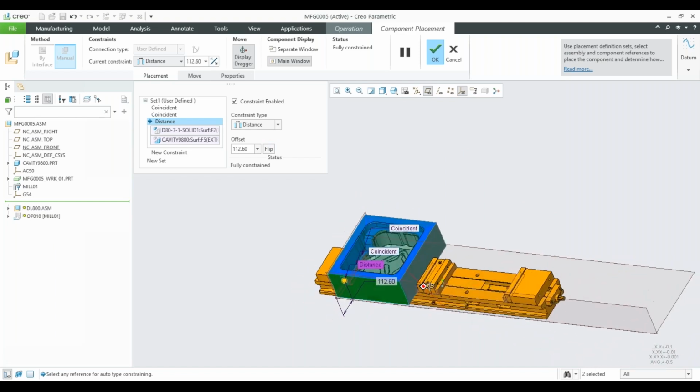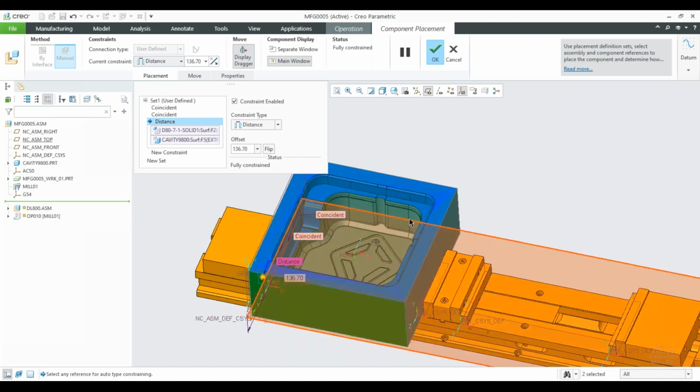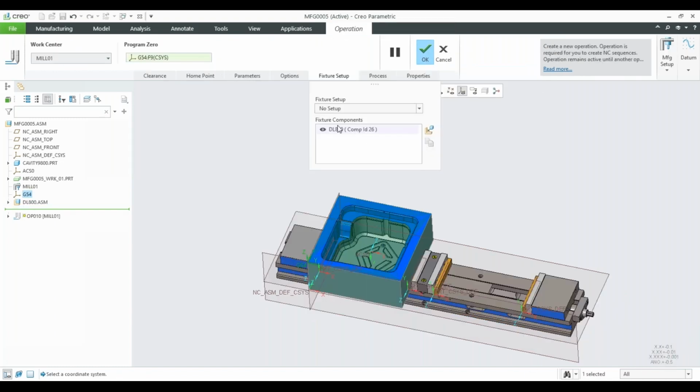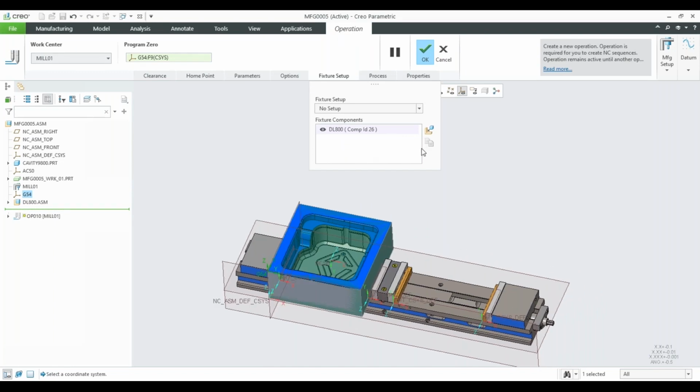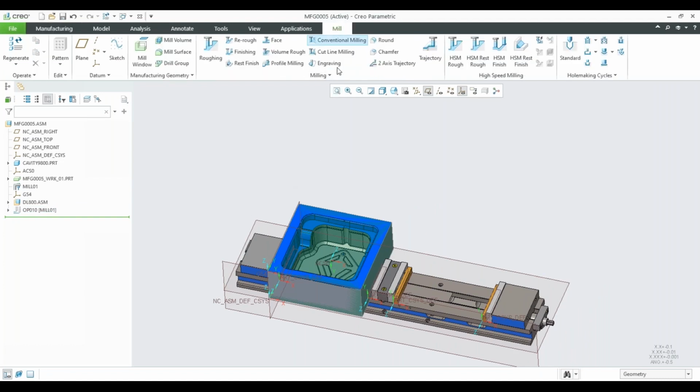If you have the exact values, use those, because if you put it wrong here, your collision detection and things might be an issue. In this example, it's not going to be an issue. I'm just going to machine the inside of my part. And we are happy. So there's our vise. That's part of our operation. And notice now that I've finished that operation, I have my milling tab, which means now I can start machining this component.